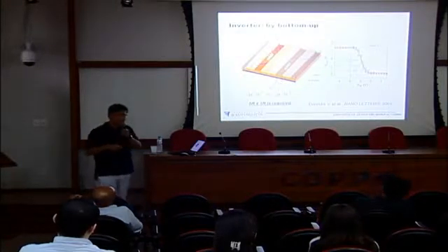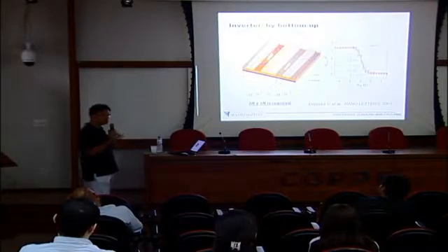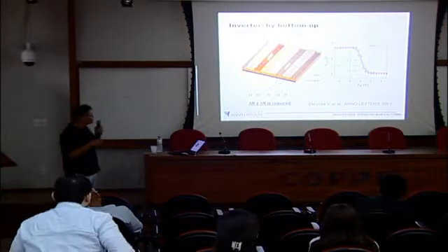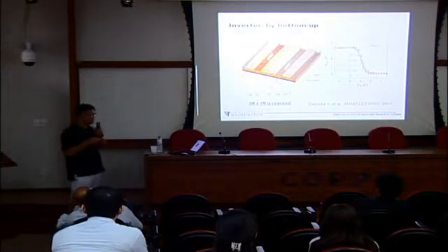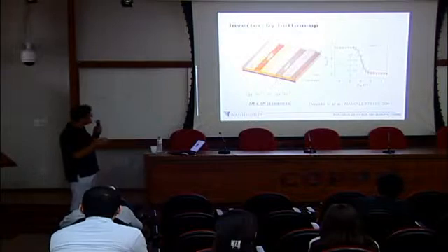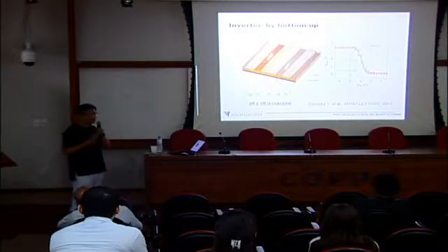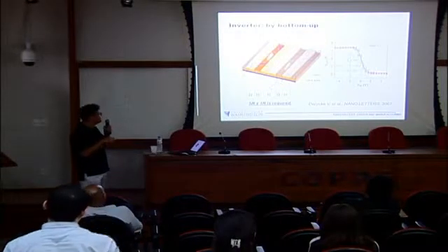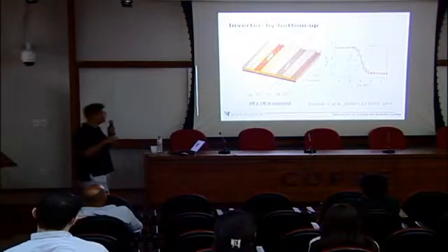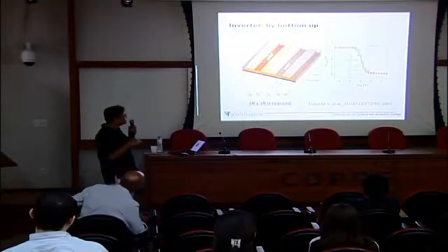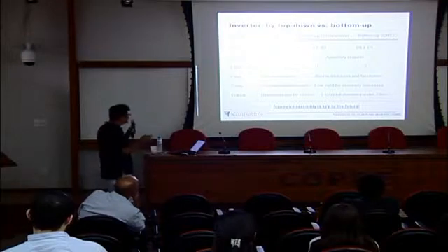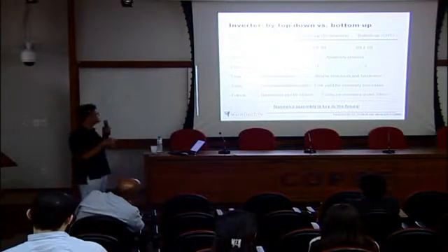Electrodes were fabricated first, okay, in one direction, and then in a solution there are a bunch of nanotubes. Okay, a very high concentration of nanotubes are there. And then the solution was randomly dried out on the wafer, and some of them were deposited like that. But it cannot be perpendicular to the orientation of electrodes, right? And anyway, one is identified. Usually it takes a few days to find 1 nanowire. It's very weird. Even though they are randomly positioned out there, it's very hard to identify a nanowire on electrodes. The assembly process is really challenging, right, for these bottom-up methods.